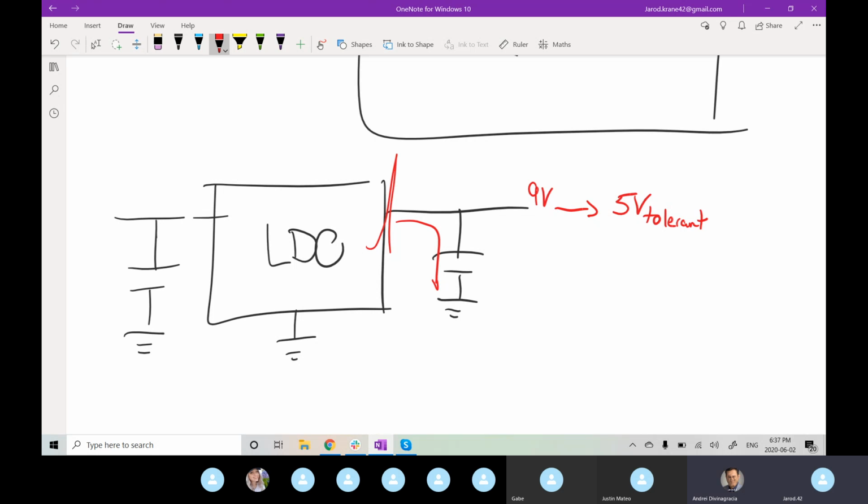Yeah, maybe if we were to pull up the actual data sheet, there might be some internal capacitance setup that would do a little bit of the suppression. But in basically every application, you'll see they tell you to put these, and they'll tell you exactly what level of capacitor rating you should be using to efficiently use this.